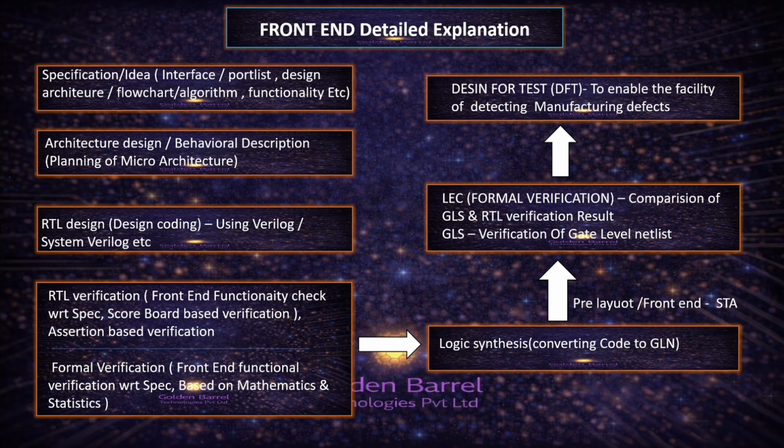Even after synthesis, we can do STA, static timing analysis. But mostly STA happens in the back end, and that is more important and more accurate. This we can treat as pre-layout STA, and that we treat as post-layout STA. This is front-end STA. This is not compulsory, but it can happen.